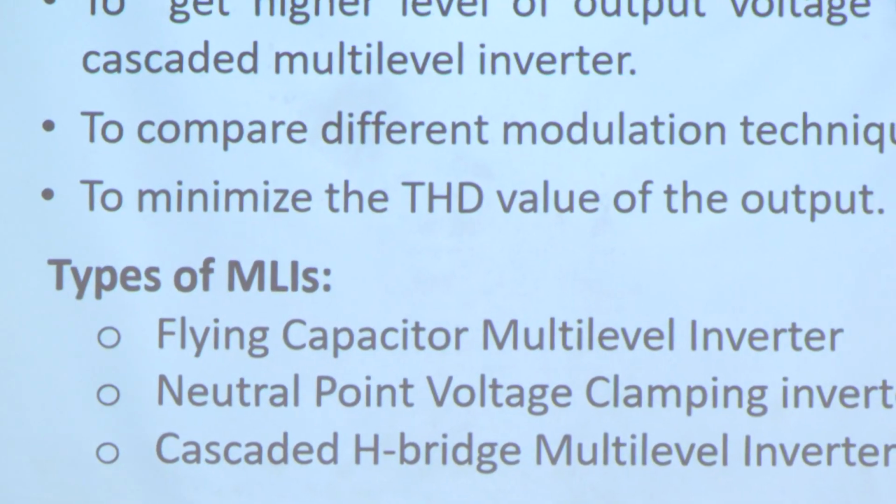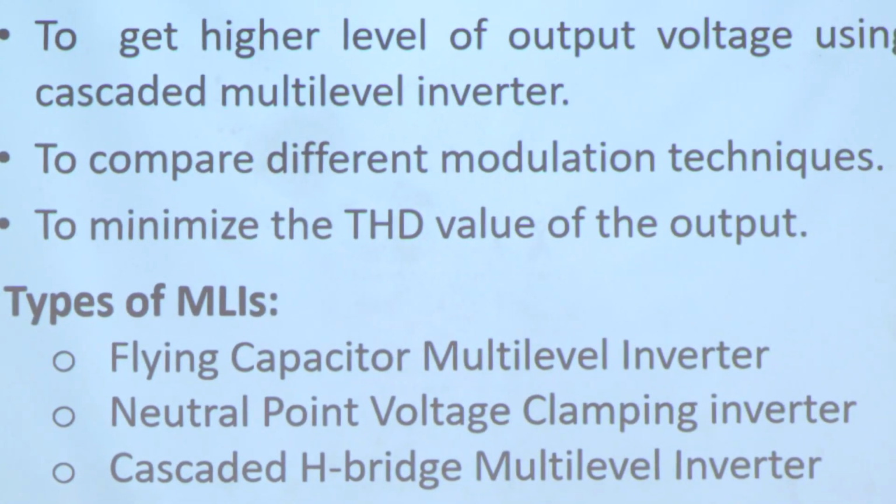By employing other types of multi-level inverter topologies, such as the flying capacitor or diode clamped multi-level inverter, we also get that. But among these three types, the modularity is found more in the cascaded H-bridge multi-level inverter topology.